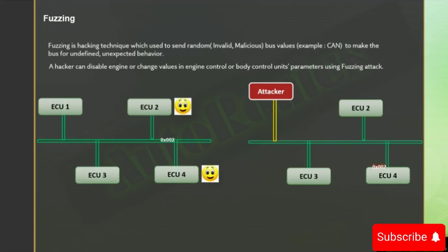So what will happen is these 2 ECUs which are subscribers of these messages may get confused. 002 will have the actual values of the vehicle, or the actual vehicle functional behavior, in the message, but the hacker's message may have only zeros, let's say. So if two different values are coming on the same arbitration ID, the subscriber ECUs get confused. Those who have worked with CAN messages practically will have faced these scenarios.